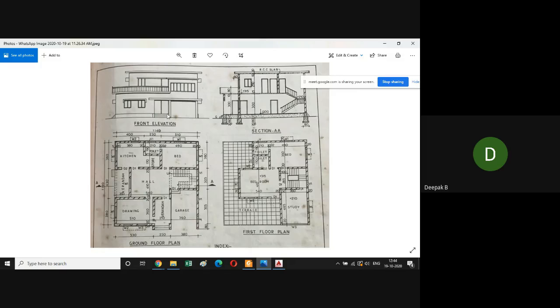After that, you have to take in the height dimensions from the drawing that you have. Dimensions, it should be mostly 45 centimeters to the top of the plinth, and after that 300 centimeter or 3 meter. 3 meter is the usual height that is provided for each floor. So using these dimensions, you draw the elevation here. Okay, you can take reference from here.